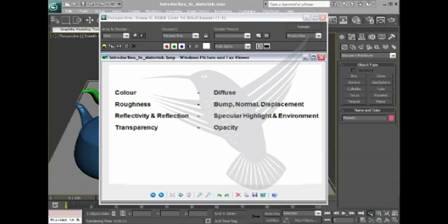But if I've got something that's up close and I want it to look detailed, I'll probably use a combination of a displacement map to give me my low frequency displacement and a bump map to show me my high frequency displacement. An example of that would be something like a brick texture, where I would use displacement to displace each one of the bricks from the surface of the wall, and then I would use a bump map to show me all the pitting on each one of the bricks. Okay, so simple explanation there.